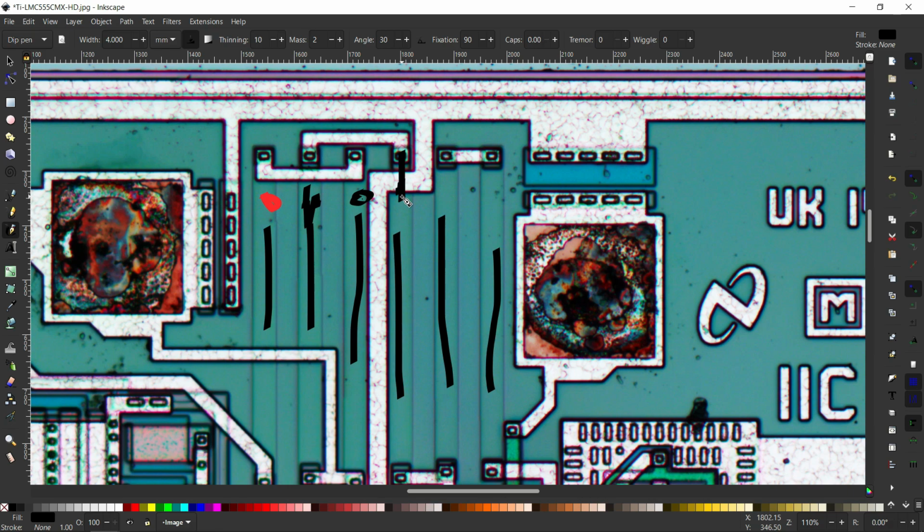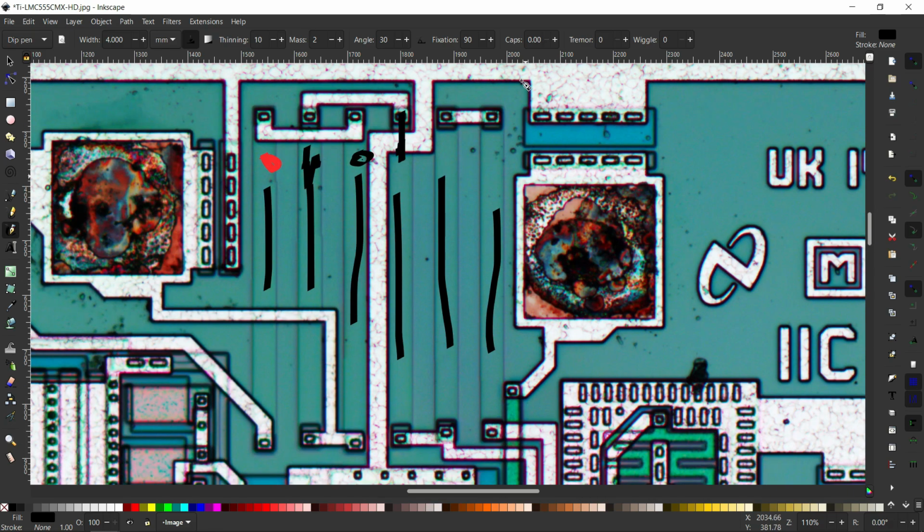They have implemented an interdigitization structure here, but for the first resistor, they have not implemented any kind of matching pattern. They just kept it side by side. The first resistor here, whatever it is there, is directly connected to the other resistor, which can create a 5k resistor.